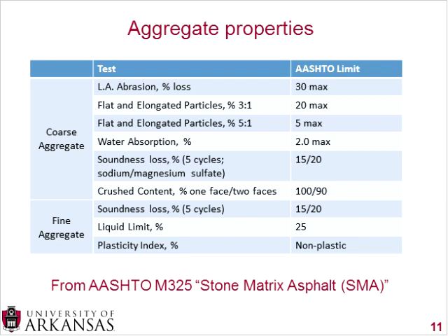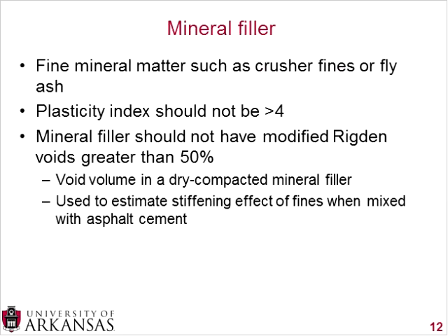These are generally seen in soils testing, but because the P200 material, the very fine material, can be quantified through the liquid limit and plasticity index, and because that's so important for your SMA mix, they incorporate those numbers into the SMA specification to make sure you're getting the property that you need. That's the aggregate properties.